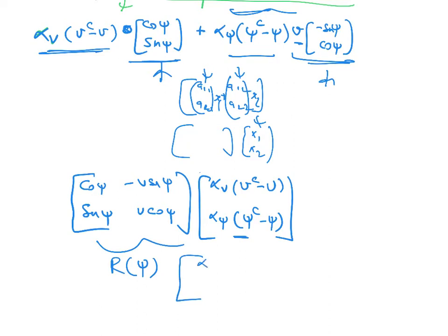See, remember, we don't know alpha v and alpha psi. That's one important thing I should have told earlier. So this is our theta. I have to separate this theta out so that when I do the cancellation and all, it is there. So I should write this as the diagonal matrix alpha v, 0, 0, alpha psi, multiplied by v commanded minus v, psi commanded minus psi.